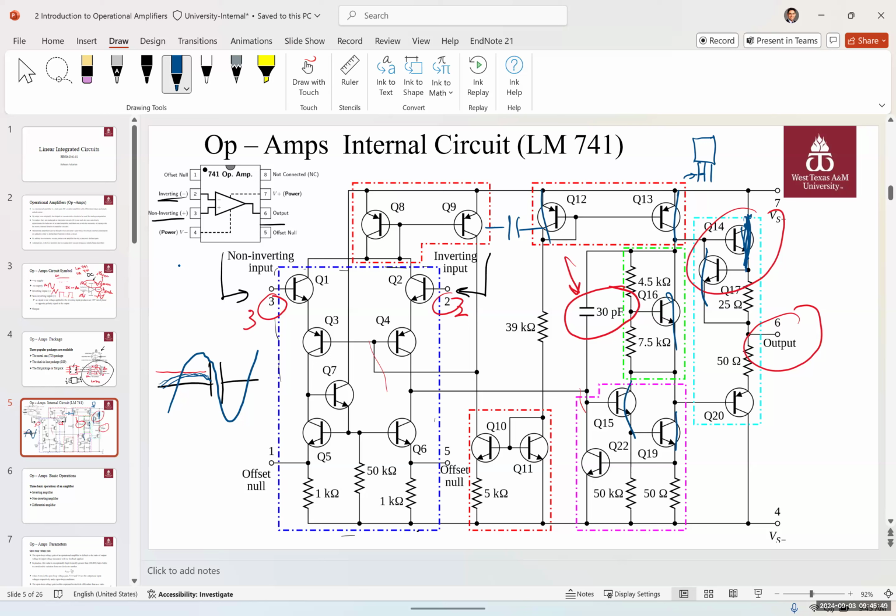So with these op amps, when you have more transistors, you're limiting your frequency response. These op amps have limitations on their frequency response, and I'll explain in later slides how we can overcome them. But this slide is in general to show you a normal op amp is made out of 20 transistors, for example, sometimes up to 100 transistors, and so on.